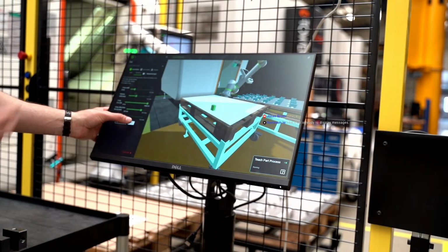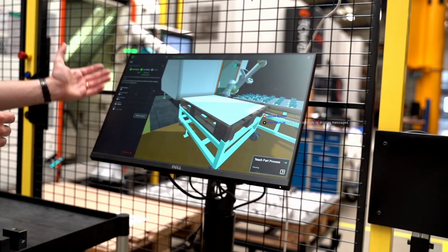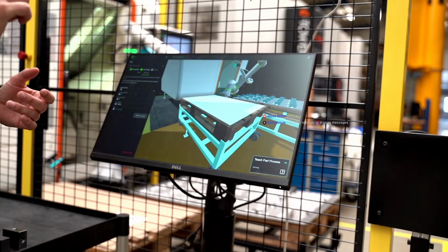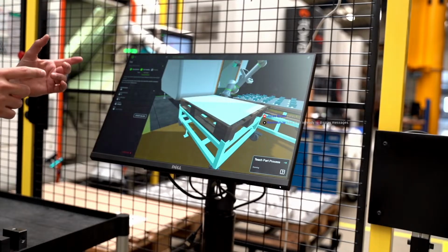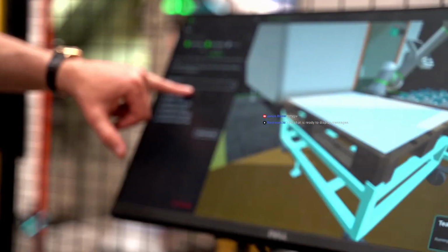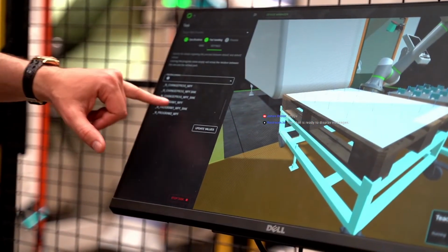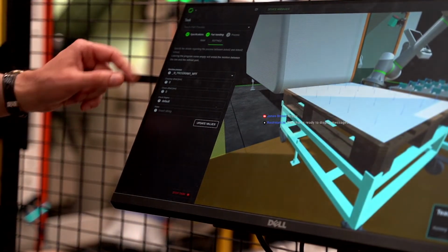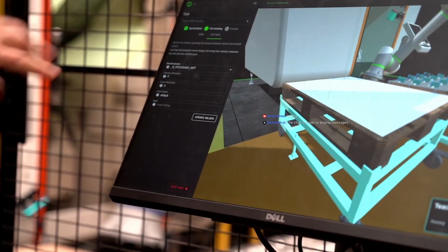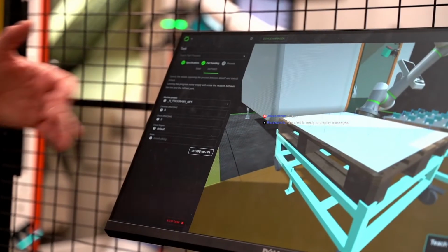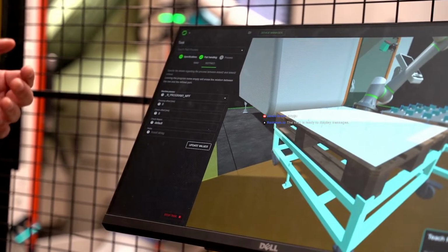And the same for the refined part, and then the last step, as we were saying before, is connecting the part processing with a program on the machine. In this case, you can see we read the list of programs directly from the machine, and then we can just select one to run. And then we can add some extra parameters that depend on the part. For example, some offset for the cleaning, or some offset for the placement.